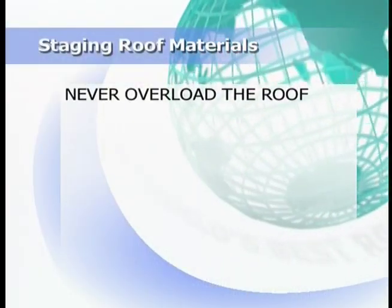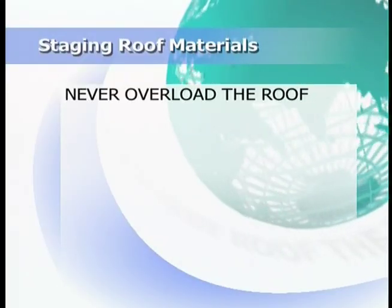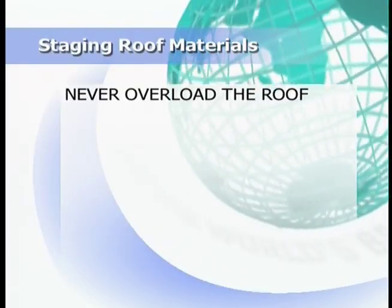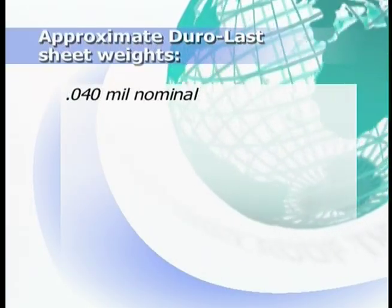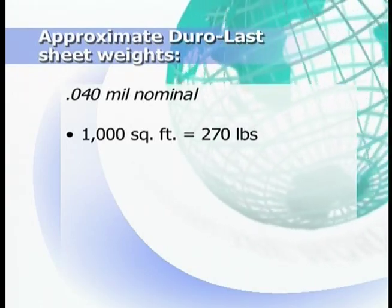Never, repeat, never endanger others or yourselves by overloading the roof. It is advisable to check with the building owner on all structural support limits before loading materials on the roof and know the approximate weight of different Duro-Last roof sections. For 40 mm nominal thickness, 1,000 square feet weigh 270 pounds.